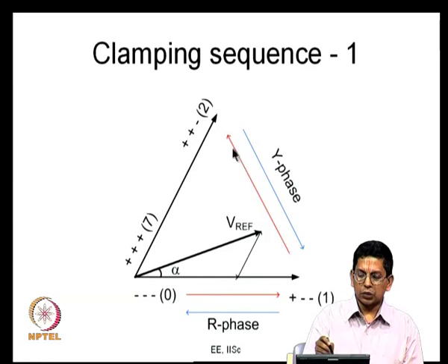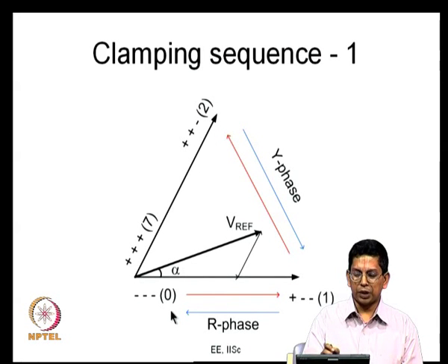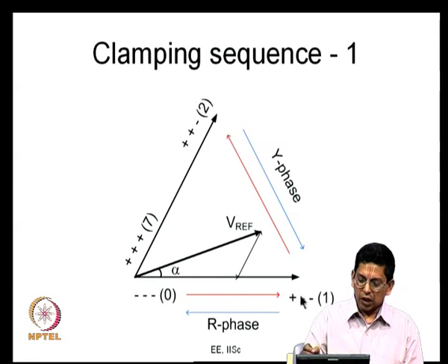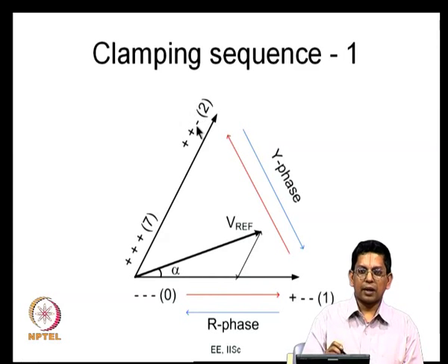So right now we will just look at the pulse width modulation generation of PWM waveforms. You see that there is one switching less, you go 0, 1, 2, and in the next subcycle you can come 2, 1, 0. So what happens because of this is the B phase, you see it is always negative here, the B phase is getting clamped to the negative DC bus.